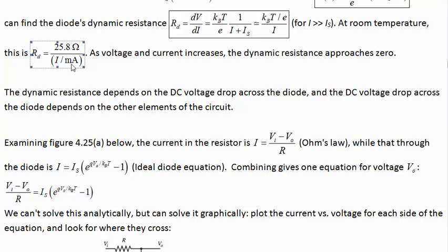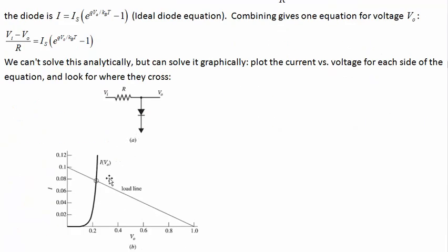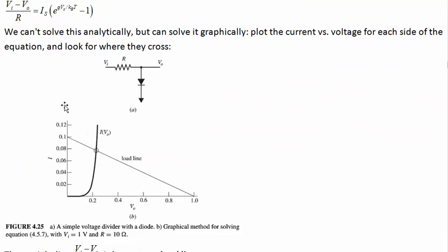current. And you may have been thinking, okay, well, why even define a resistance? Because this is going to be changing all the time with current, so we can't treat the diode like a resistor. Well, if you have a DC voltage applied with a small AC ripple on top of it, so the voltage maybe goes between 4.0 and 4.1 volts in AC, so it's mostly around 4.05, then you'd put in your 4.05 volts in DC to get the spot that you're at, like you'd solve the load line for that input voltage, which would be placed up here.